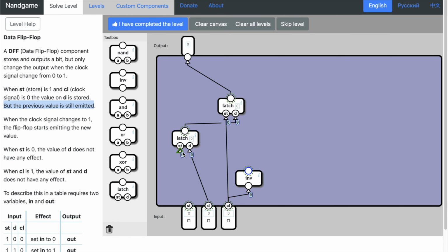No, we're going to wire up, it's not just this value. I was going to say that we wire this up to clock 0, but then we're completely ignoring the store flag. So we actually need an AND gate here. And we will store when the clock is 0 and this is 1. Did this actually connect? Yes, it did. Oh, that's a terrible bug.